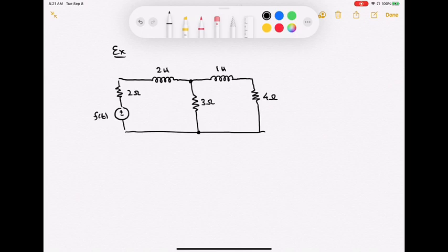You've seen this sort of stuff back in your circuit analysis days. You've been able to see these as a type of circuit that you should be very comfortable with in both modeling and solving. I haven't yet designated any kind of output variable. I'm going to allow myself 2 output variables here. This is typical of how we'd approach an analysis of this anyway. So I'm going to take a look at this first loop current, and I'm going to let that be one of my output variables. I'll call that Y1, and I'll look at the second loop current, and I'll call that Y2 of t. So now I've got a complete circuit.